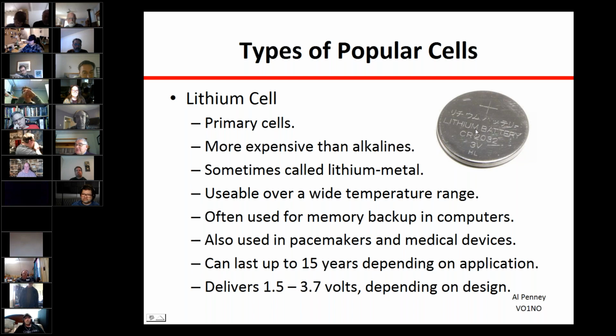And if you want to do a proper job and you figure you're going to have the piece of equipment for a long time, instead of having to spot weld the terminals to the battery, just put in a battery holder and solder that in place. Okay, Roderick, there you go. They shorten the life of the cell, yeah.